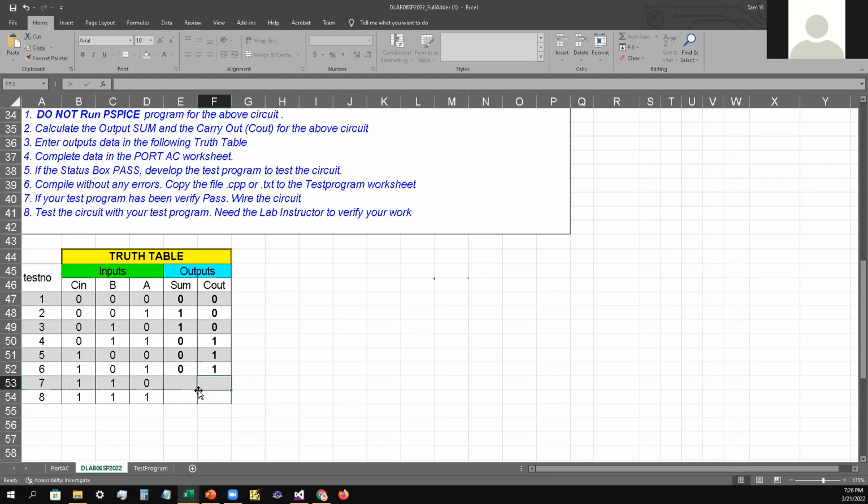And that 1 gets carried over to the next. I don't follow that one. To me, the 0 and the 1 should have been 1 and 1 plus the carry over. Okay, carry in. So this one actually goes into this one. You're just adding it. 1 adding to 0 is 1. And then that would be a total of 10. So therefore you put 0 and then the 1 will carry over to the carry out.